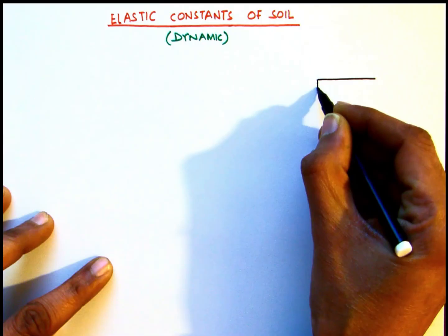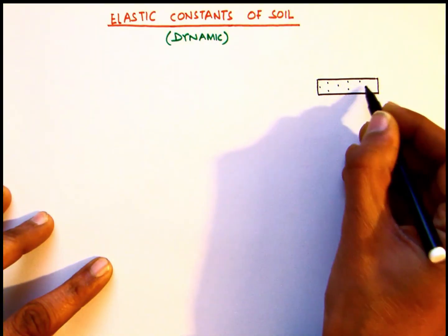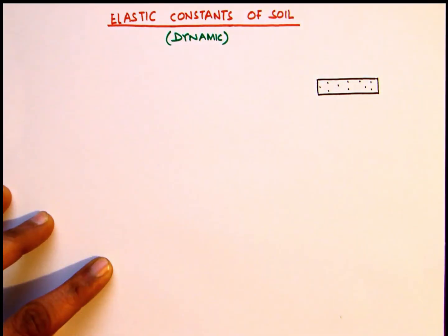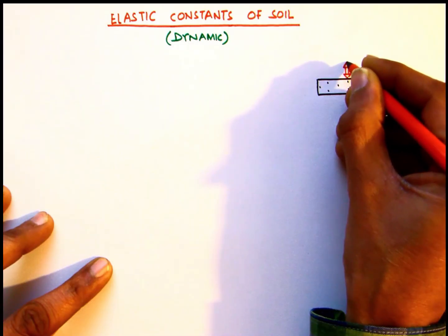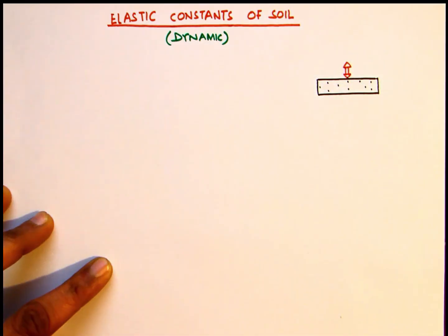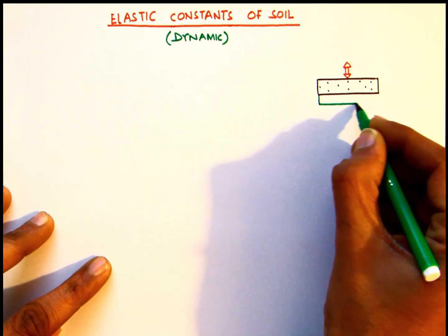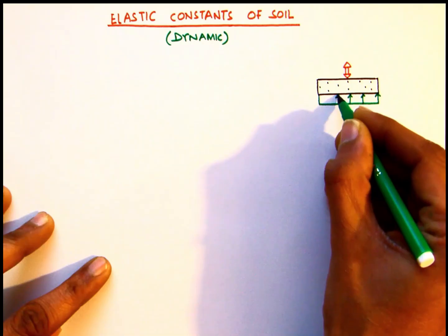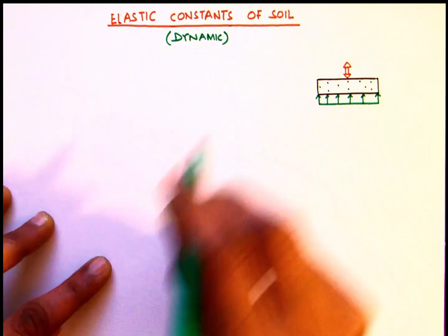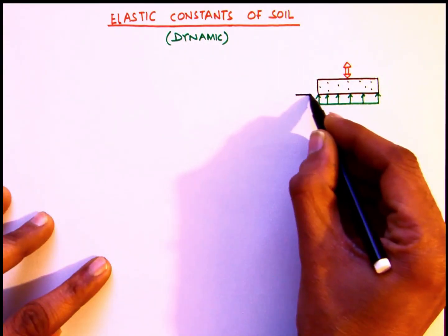The simplest type of vibrations undergone by the block foundation are the vertical vibrations. Let's say the block is under pure vertical vibrations, say a reciprocating type machine is operating and there is no eccentricity, then this would generate uniform stresses in the soil below the block foundation, and this would be compressive in nature.